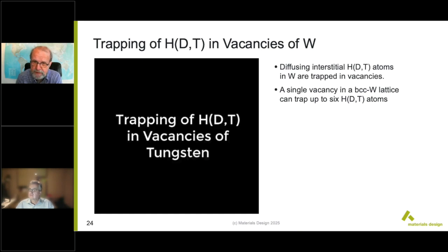Now, in contrast, when we looked, for example, at the phase transformation of ZrO2 from the monoclinic to the tetragonal, there we used an interatomic potential, which was trained for a large variety of different zirconium oxygen systems, so maybe of the order of 5,000 different structures, and then you basically follow the protocols of a typical molecular dynamics simulation. You equilibrate and then you do a production run.